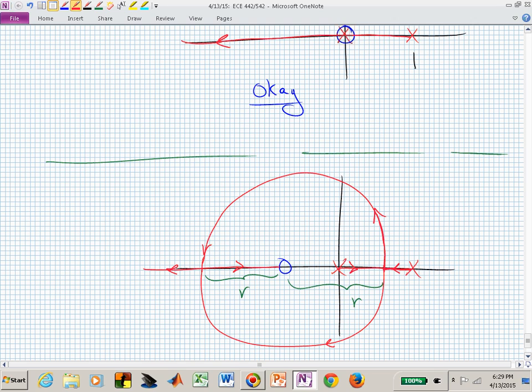Is this one going to be more challenging to try to control? And where is that blue circle going to be located? One option is if it slid all the way to the right and just canceled that pole, what happens to this root locus?